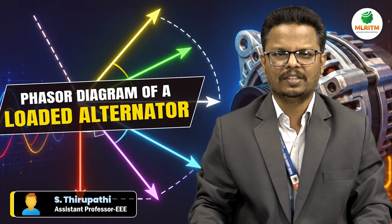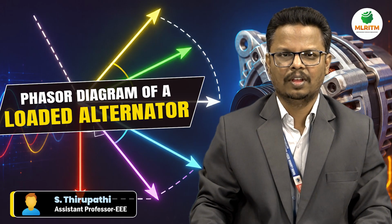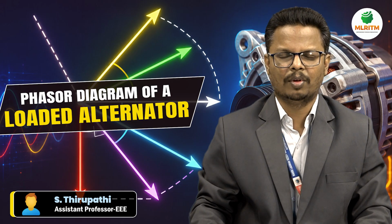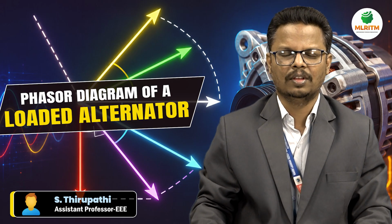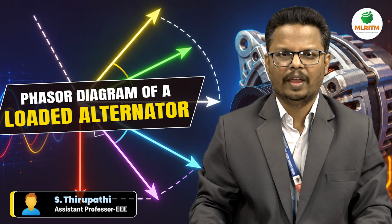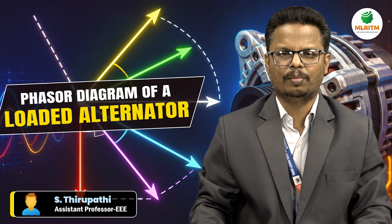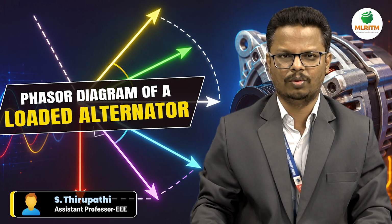In the resistor, it carries the current, it has a voltage, and there is a power factor, and that power factor is unity. Why? Because the angle between voltage and current is 0, and the current is in phase with the voltage, so the power factor is unity for resistive loads.